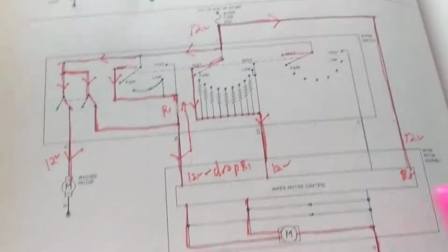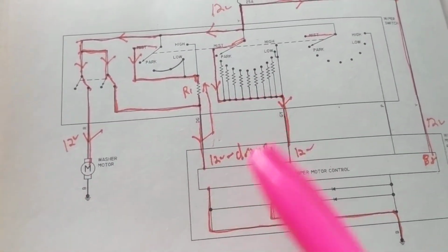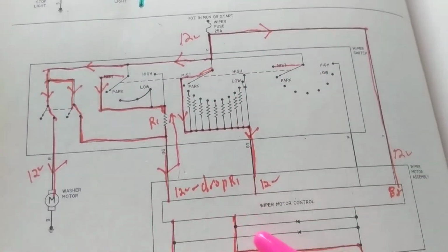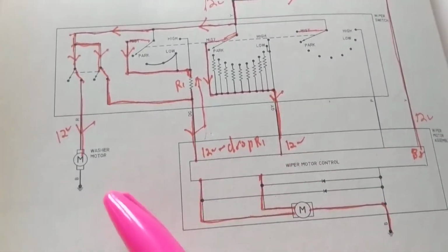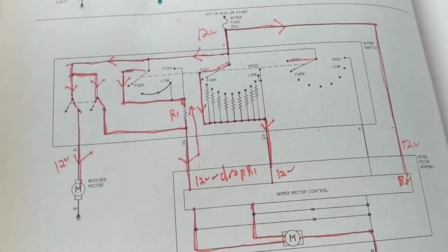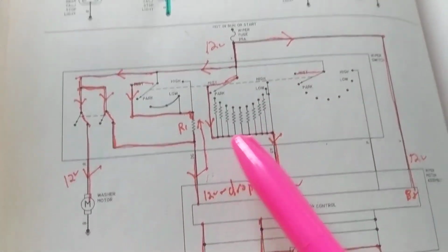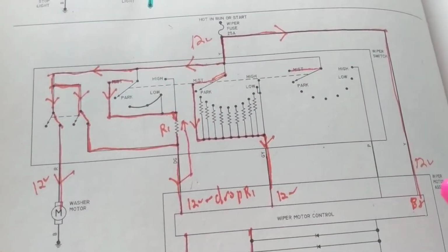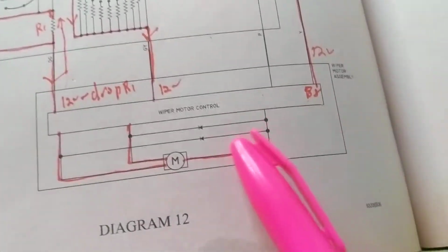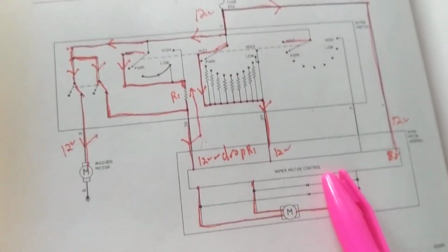Like I previously stressed, you always go for key components and something that catches your attention. In this diagram, something that catches my attention are the motors. It's something different that I haven't seen in the other schematics. The switches over here catch my attention. This fuse doesn't catch my attention because there's many fuses. This catches my attention, the control module over here for the wiper.